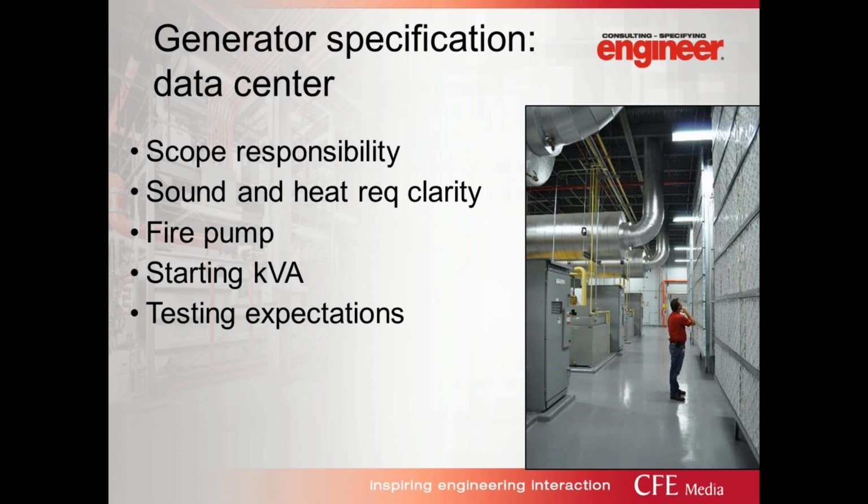And then testing expectations. It's just not for commissioning agents. You need to be very, very clear in the specification of what you expect on the front end for factory acceptance testing, as well as site testing, as well as commissioning assistance. That can be a very large scope or a very minimal scope. You need to be very clear so that you get the best bang for your buck.